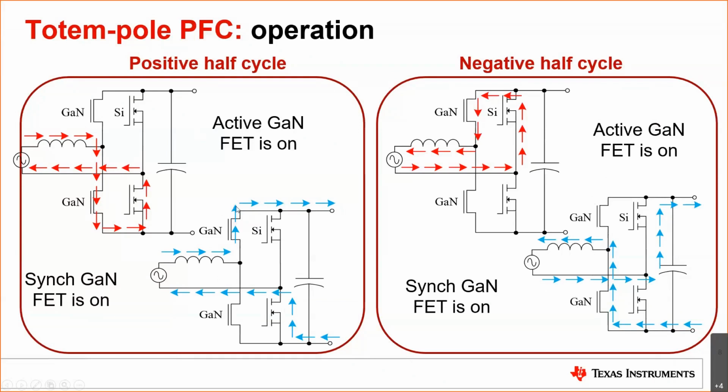And this will maybe also explain a tiny little bit why we only need GaN actually in 1 half bridge. If you remember, the silicon-based half bridge is actually only switching at 50 Hertz, or the frequency from your line input. So from a technical aspect, it would actually not be required to have a fast switching FET here. On the other hand, since this is a hard switching power topology, GaN is actually very good in this perspective versus silicon or silicon carbide FETs, because we do not have any reverse recovery losses here, but that's also something that we will check in the next slide.